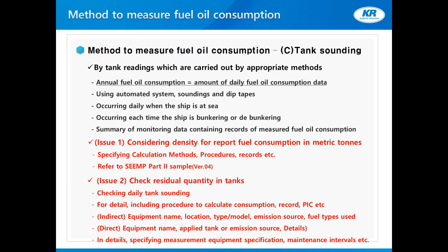Regarding density conversion of fuel oil consumption into metric tons, please specify calculating procedure. If you are using sample version number 4 of the SEEMP Part II, you can pass this issue. For checking residual quantity in tanks, in other words, bunkers remaining on board, tank monitoring should be done every day. And for more detail, please add procedure about consumption calculation, relevant record, and person in charge.